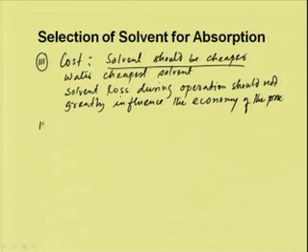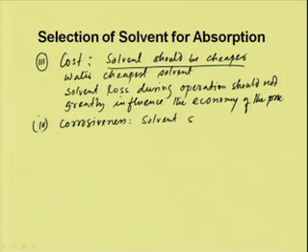Another important parameter is corrosiveness. The solvent should be less corrosive, so that we do not need to use expensive material for the construction of the absorber. Another important parameter is viscosity.